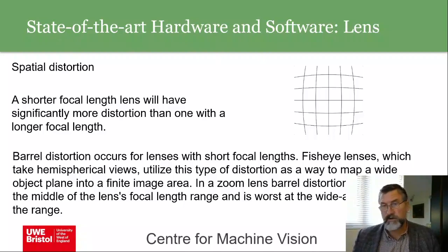But you can imagine that if we're using this in a metrology or measurement application, all this kind of distortion can lead to considerable errors in the ability of the lens to be used to give accurate measurements. If this error is constant, doesn't change, then you do stand a chance of compensating for it. And that's what the LabVIEW thing I mentioned does.